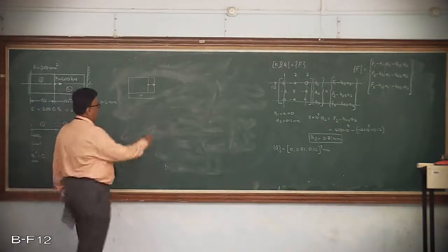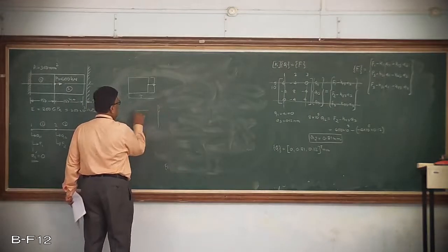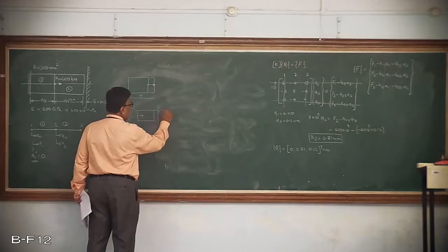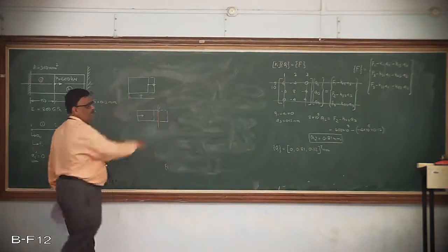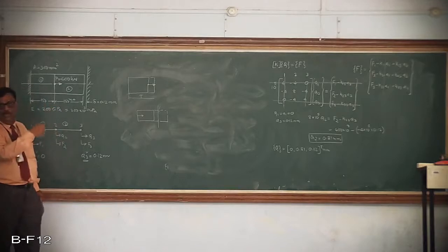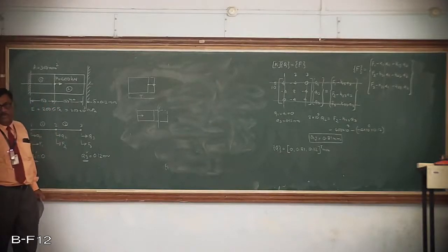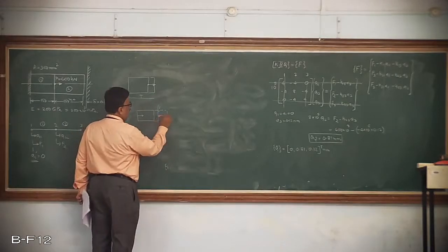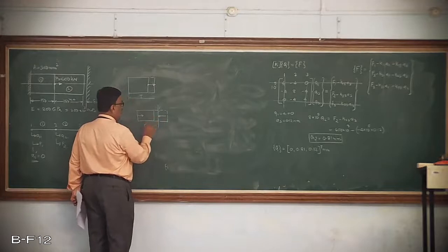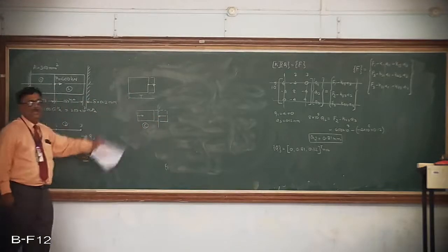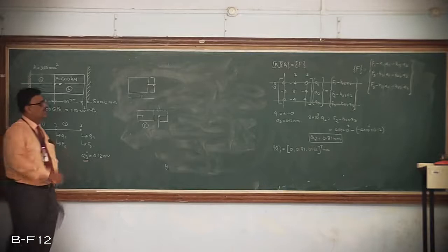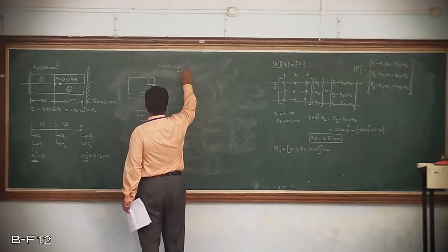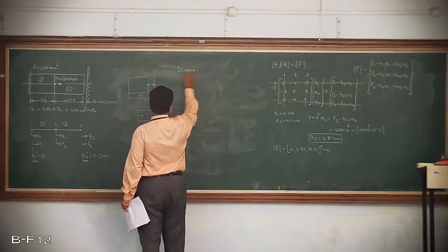in nature. Whereas in the second member, the same force is trying to push it, and once it touches the wall, the remaining is all prevented. Even though the member would have deformed to that extent if the wall had not been there, because of the presence of the wall the deformation is prevented, and this will induce a compressive stress. So we will see the results, and we should get similar types of results. Therefore, now I will write the stresses.